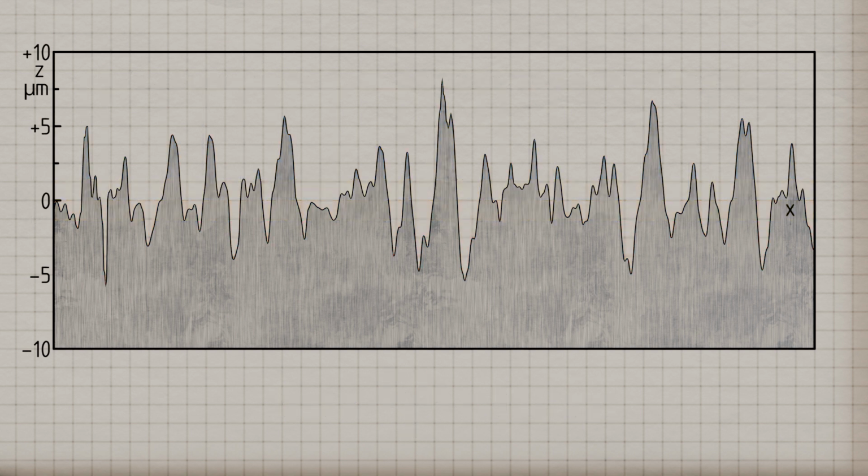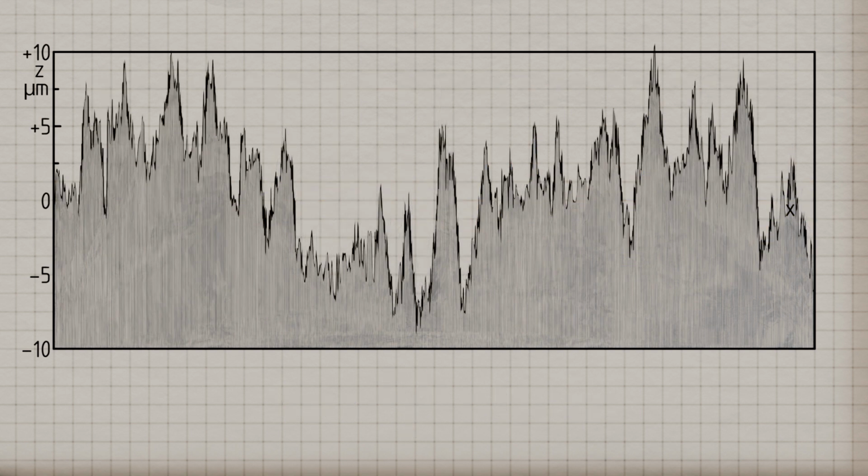Finally, the recorded surface profile should be examined more closely once again. As previously explained, the scanned surface profile contains different components of short and long wavelength oscillations of the stylus tip. Both the short wavelength, which means high-frequency oscillations due to the stylus tip vibration, as well as the long wavelength, which means low-frequency oscillations due to surface waviness, must be filtered out.